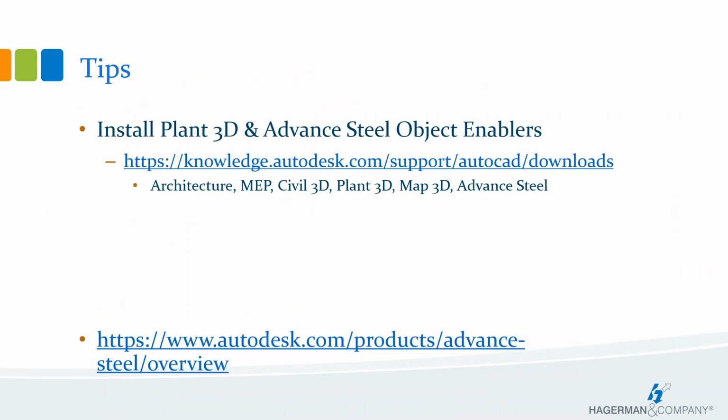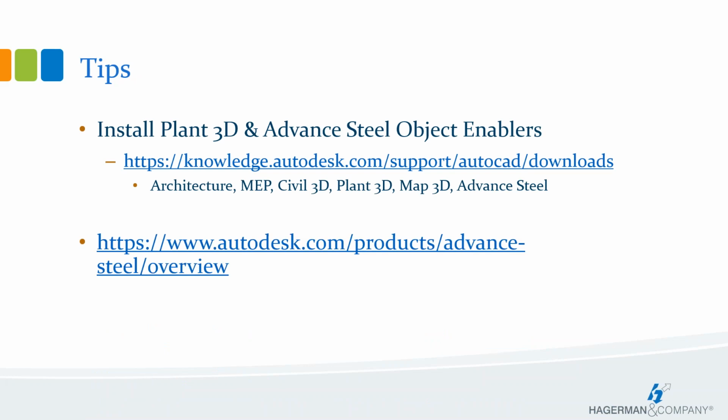If you're using multiple AutoCAD-based products, in this case we are, or if you're using Navisworks, you'll need to install the object enablers for Advanced Steel and Plant 3D. Those will enable the model objects when you're doing your XREFs. For example, when XREFing a model from Advanced Steel back into Plant 3D, you'll be able to see the connections and all the features that Plant 3D can't produce. So when you touch on those, you highlight them and you look at the properties, you'll get that information. If you don't have the object enablers installed, you'll get the proxy information dialog, and some objects won't show correctly.